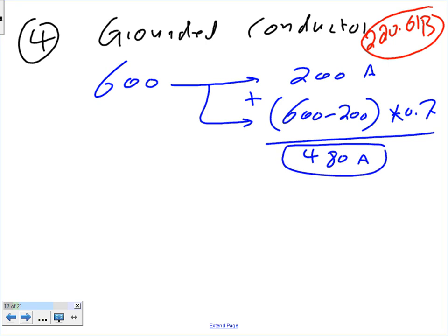So we're just doing this pure exercise, but we would go full on a receptacle panel, yes. I wouldn't size a receptacle panel more than 300 amp. Actually, 225 is the largest. When you do size the receptacle panels, add all the loads. If you end up with a panel more than 225 amp, what do we do? Just split them into two panels. Like Chris in our project, it would be one 225 amp panel on the first floor and another 225 amp panel on the second floor.